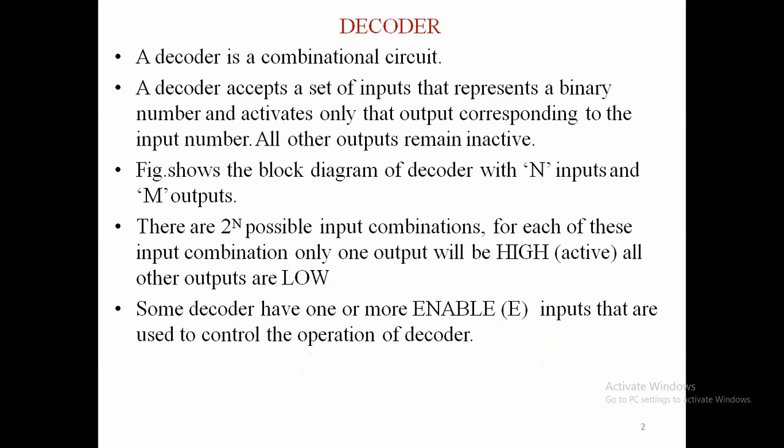For example, in the 3 line to 8 line decoder, if a common enable line is connected as a fourth input of each gate, the output selected by the ABC input code will go high only when the enable line is high. There are different types of IC used for the decoder, that is the 74LS138 decoder.